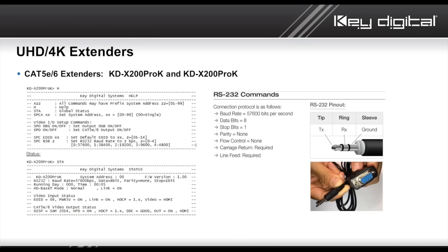Of course, I'm not the one to guarantee that, but it's a fact of life any longer, isn't it? We find that if there are HDCP problems in your system, it's typically based on the wiring. Some electrical interference, for example, comes in, breaks the DDC, that's the digital data channel, and kills the HDCP. So that debug mode is very, very useful.